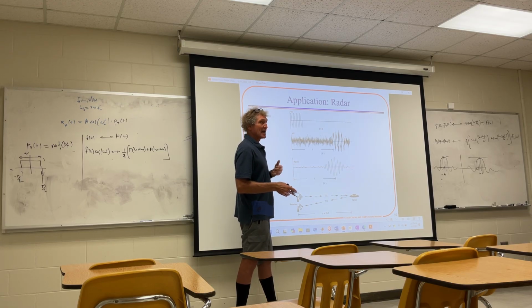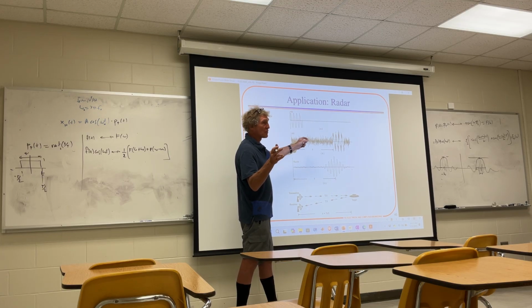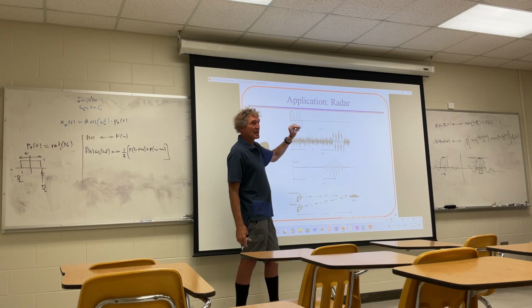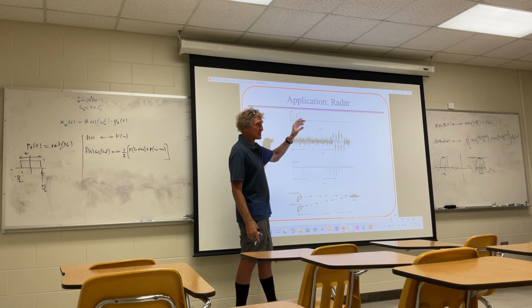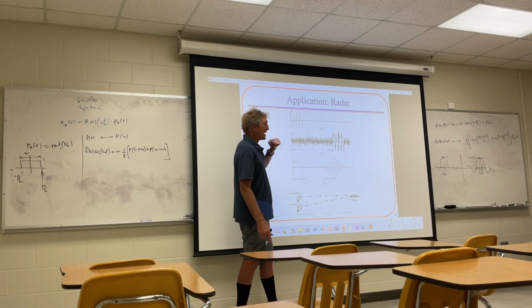Then we take that and we simply do a cross correlation. In his, he does it at the high frequency. They can do it this way. It's very hard. It's called digitally defined radar, where they literally take the signal as it's coming into the antenna, receiving, reflected back from the target. They'll amplify it to a certain point, and they'll go right from A to D. They won't strip off the high frequency carrier, which is, in my opinion, kind of stupid, because that's the thing you want to get rid of. And you can do it with digital processing, and then they do a fast correlator.